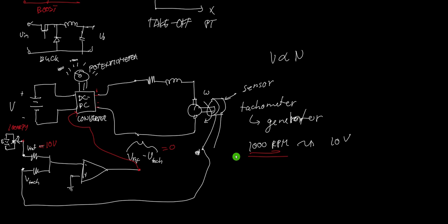So this is a complicated example, and this is what the real components of a real control system look like. If you look at these different components, it's not just one component. What we did in chapter 2 is we modeled each component. We modeled the potentiometer, an operational amplifier, an RLC circuit, and an electromechanical or rotational system. So these are different transfer functions.